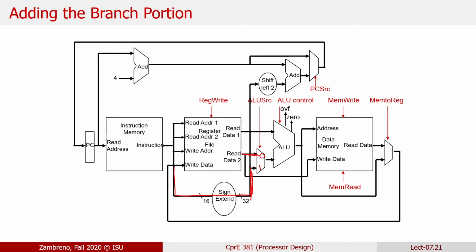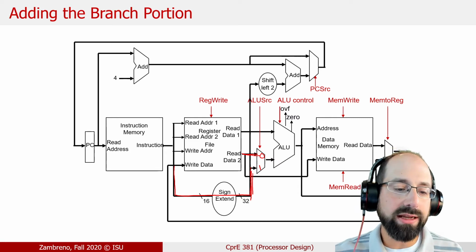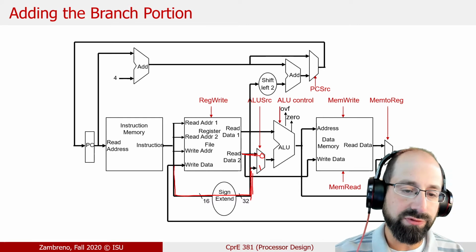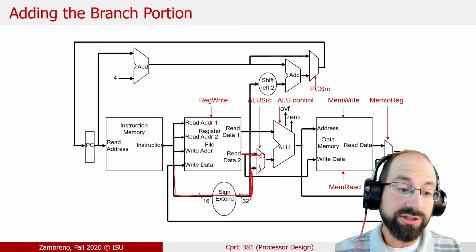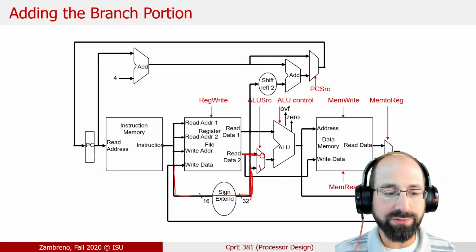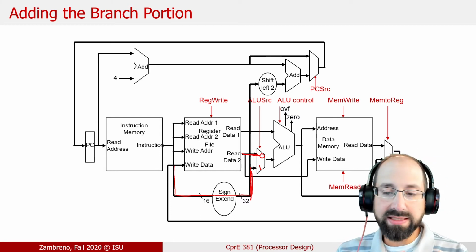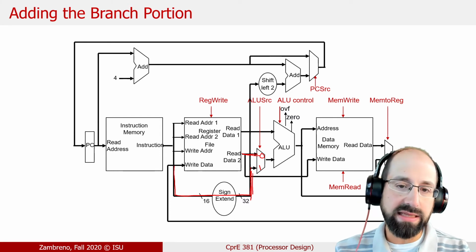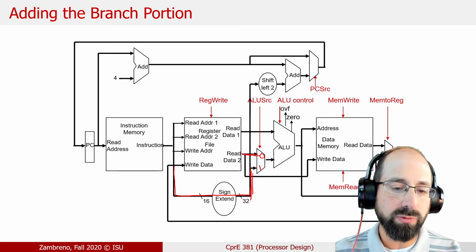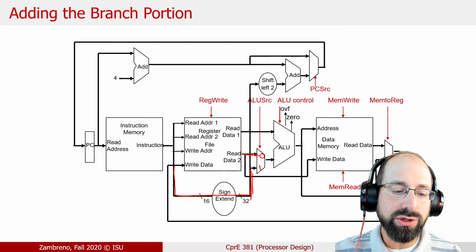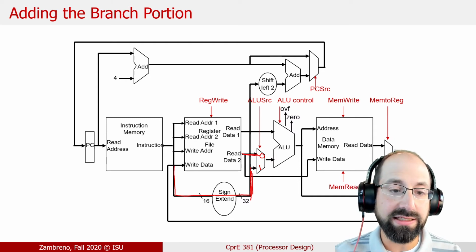So as part of our control structure for the processor, that's all that we're doing here, right? We're looking at certain information encoded directly in the instruction, and in doing so, we're generating a series of control signals from that information directly encoded in the instruction. And yours are going to potentially already look a lot different than the textbook version. Based on the Project Part A designs I already had the opportunity to take a look at earlier last night and earlier this week, everyone's ALU control scheme is going to wind up looking a lot different.